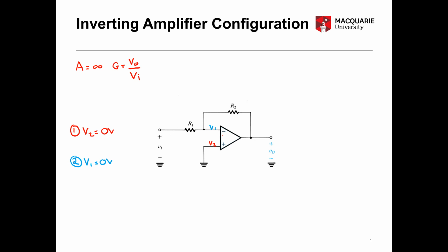So this can be a little bit of a difficult concept to get your head around, but it can be shown mathematically. If we just consider the case of the op-amp by itself, which we've looked at previously, we know that the op-amp's output V out is equal to the open loop gain A times the difference in input voltages V2 minus V1.